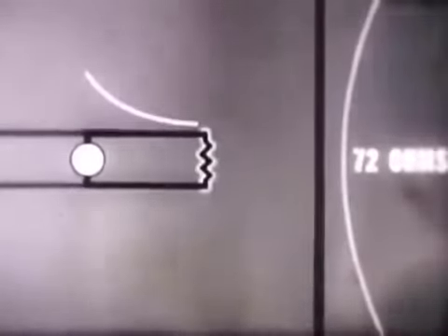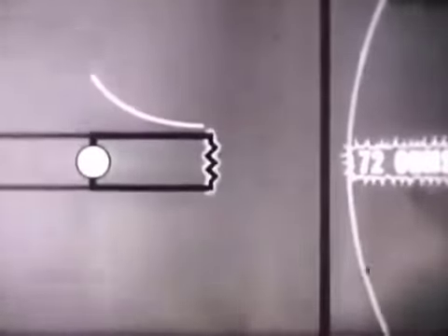Another method of impedance matching employs two lengths of metal tubing called a quarter wave matching transformer, or Q-bars. These tubes are merely the twin wires of our old friend, the quarter wavelength resonant line. In this closed line, the impedance curve is minimum at the closed end and maximum at the other. Now, supposing we put a resistor in the closed end of the line, say 72 ohms.